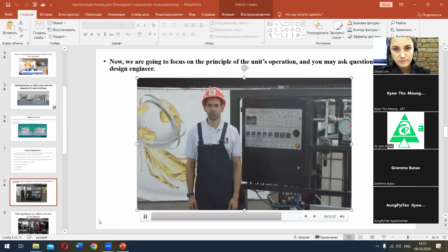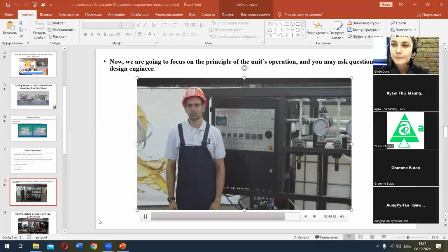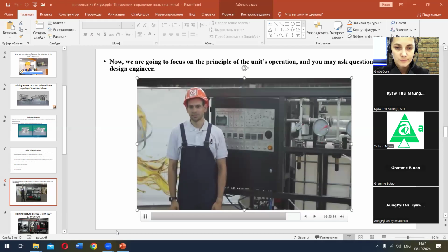The stated capacity of the unit is 2 cubic meters per hour. This value may vary depending on the formulation. Due to a high level of automation, the unit is extremely easy to operate and maintain. The unit can be optionally completed with a latex input component. The mill can be completed with a mechanical seal. The pneumatic system can be supplemented with a compressor. All of this makes the unit a simple and convenient complex for production of water bitumen emulsion.